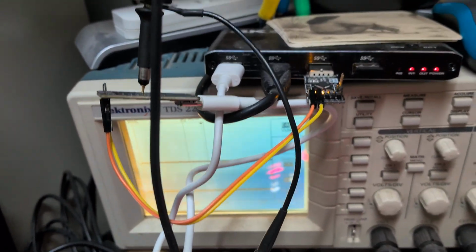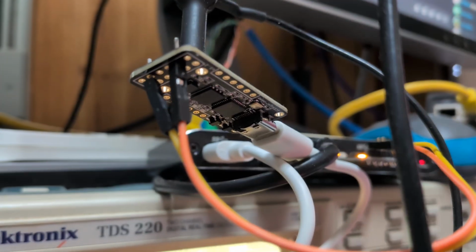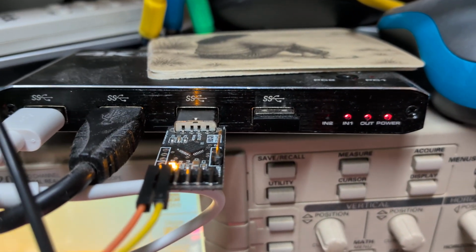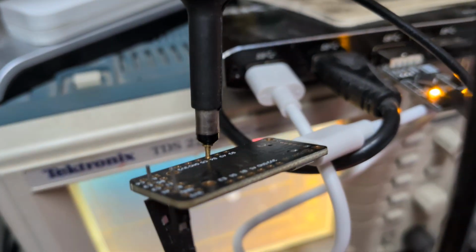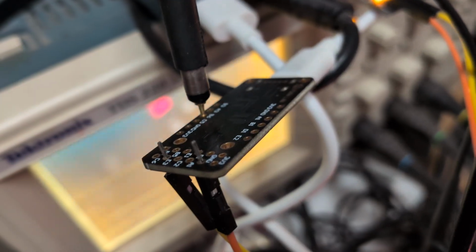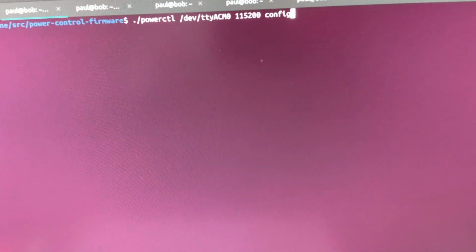Okay, let's have a look at what we've got here. We've got our low power FPGA board there. We've got our little USB UART here that's pretending to be the cellular modem so that I can send commands in to inject. I've got the oscilloscope probe on pin B6, so should we come over here for a minute? This is a nice moment to have a look.